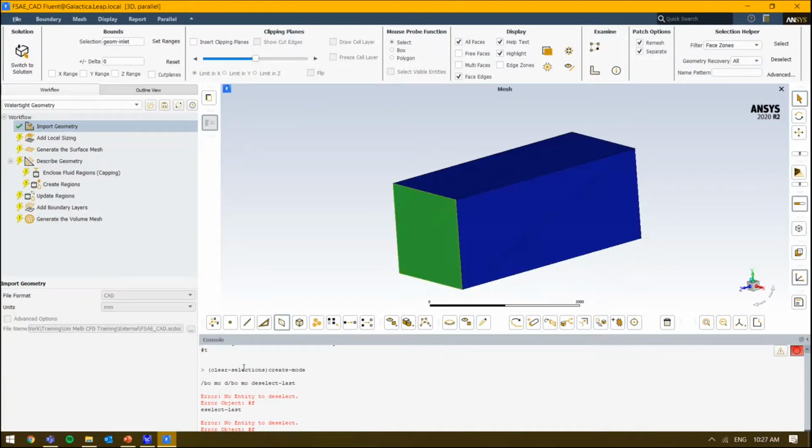It's just, remember, one of the tenets of getting a good mesh strategy is making it easy to use, right? Easy to generate. If you have to do this every single time you get a new geometry, it becomes a bit annoying, right? So having things like name selections come in cleanly from geometry, whether you're using SpaceClaim, SolidWorks, Inventor, Creo, whatever, I always recommend that, right?